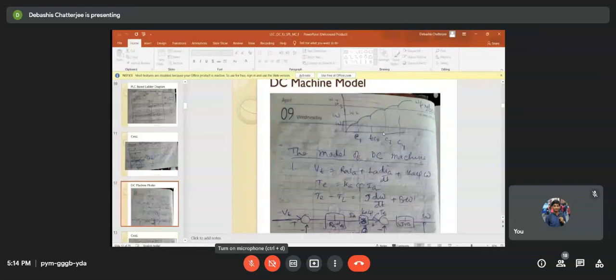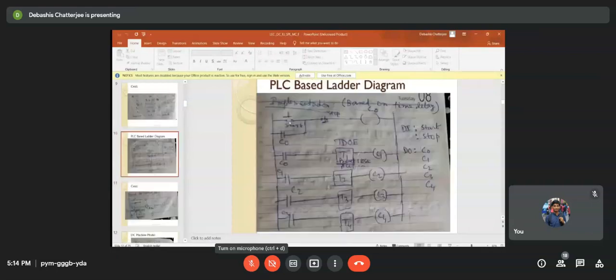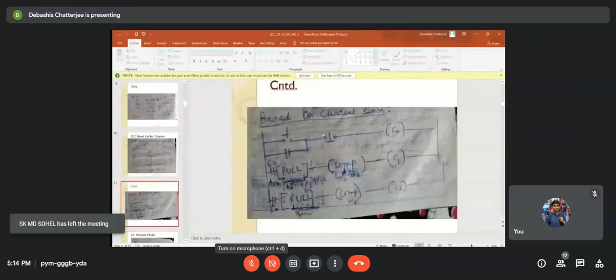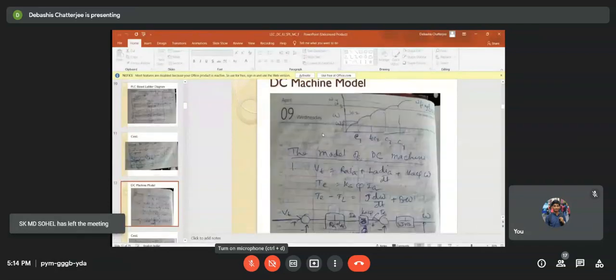So you have a start switch. Now start is an NO contact, so I have shown it as a switch just to show you. You can replace it with an NO contact, like whatever is shown for C0. So this is start, and we can have a stop. Always stop should be there, an NC contact. It will be like a cross, right? I think I have not shown NC anywhere. I'll show it later on probably. Okay, this is an NC contact.